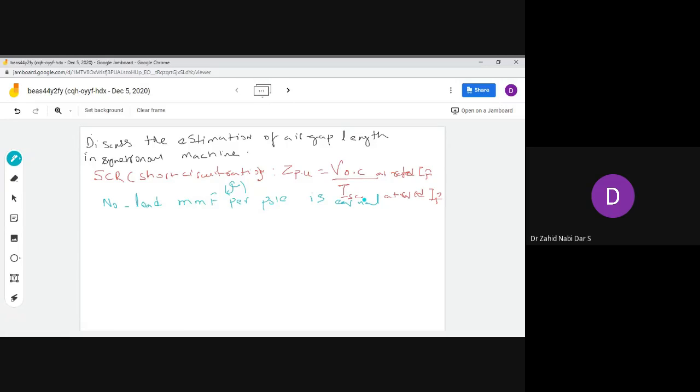Tell me. It is equal to the product of armature MMF per pole and the short circuit ratio,